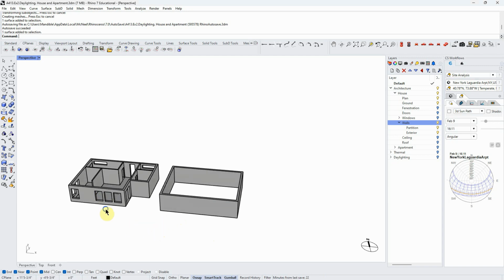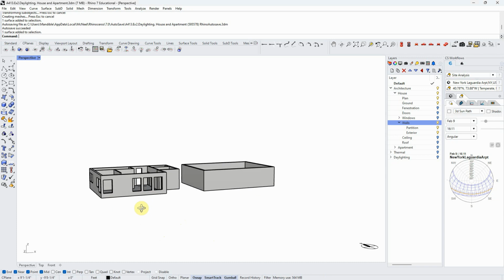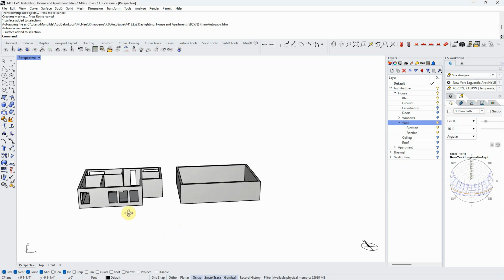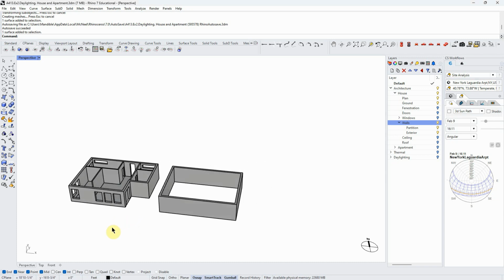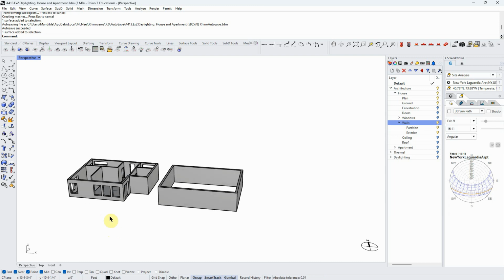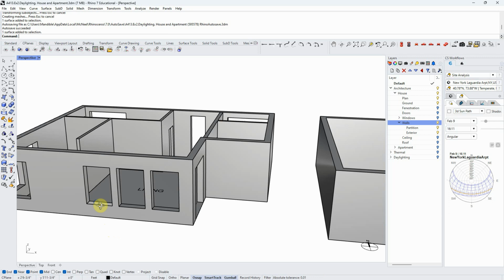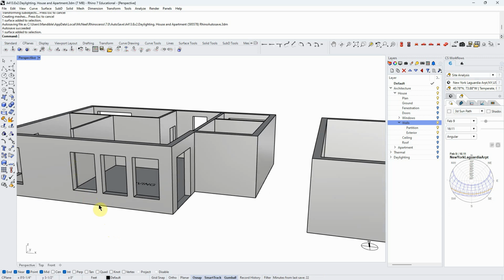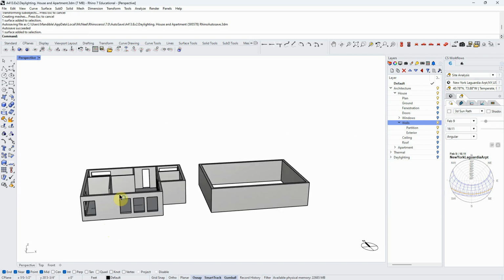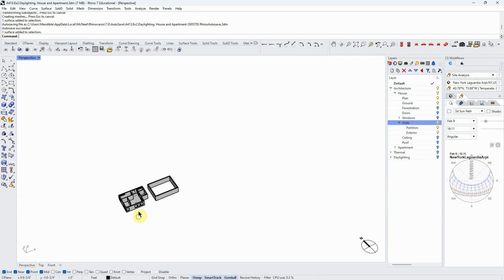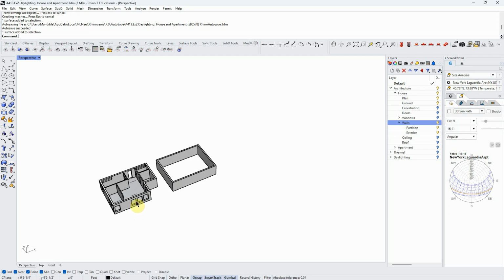Now, by the way, we can make this model either with thickened walls or not. That's up to you in terms of how you typically model. In the case of daylighting analysis, it's going to be good to have whatever thickness we think is realistic, because then that will create a reveal that will cause shadows and adjust the daylighting so it's more accurate. For thermal modeling, we're just using surfaces, so we would not use the outside.